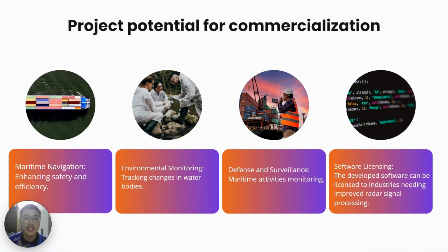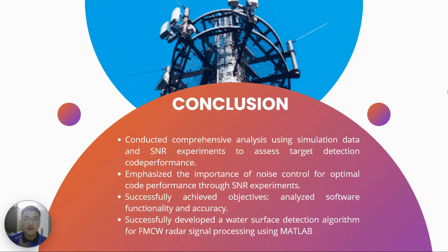So for the conclusion of this project, I conducted a comprehensive analysis using simulation data and SNR experiments to assess the target detection code performance, emphasizing the importance of noise control for optimal code performance through the SNR experiment. And then, like I said, the project was successful, we got the range estimation that we wanted. So we successfully achieved the objective, which is to analyze the software functionality and accuracy. And we successfully developed a water surface detection algorithm for FMCW radar signal processing using MATLAB.